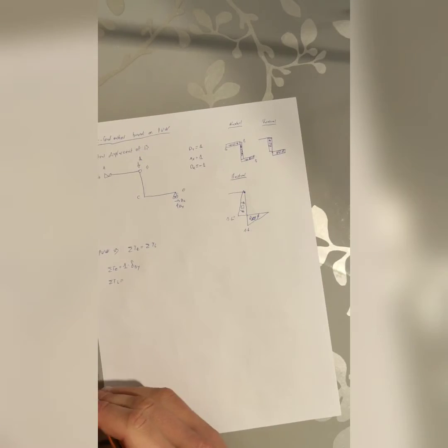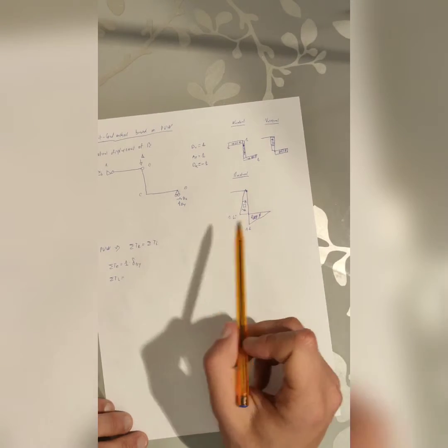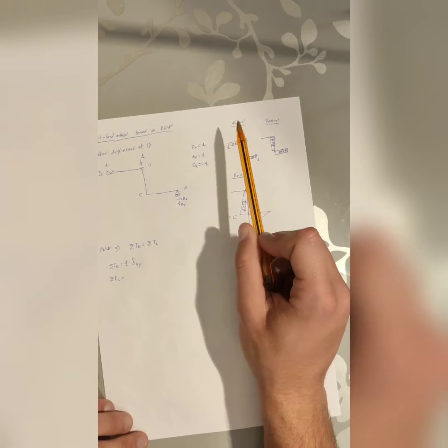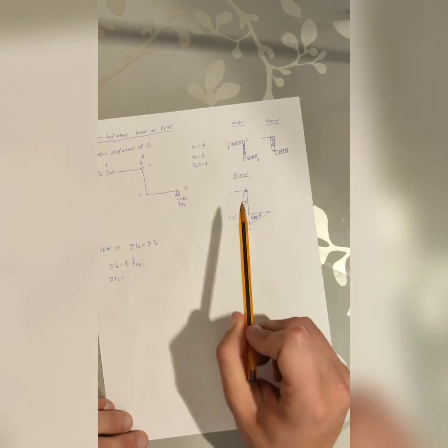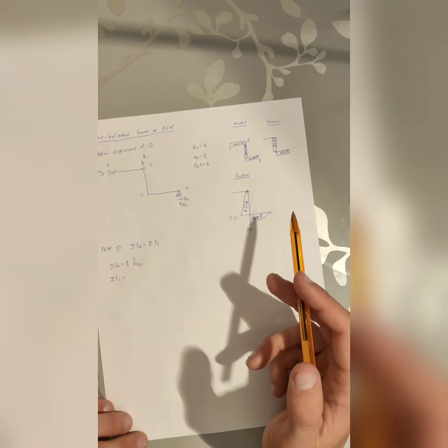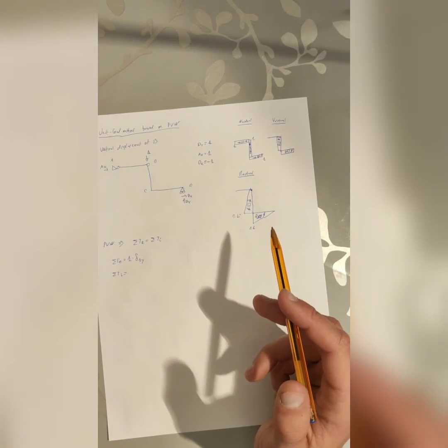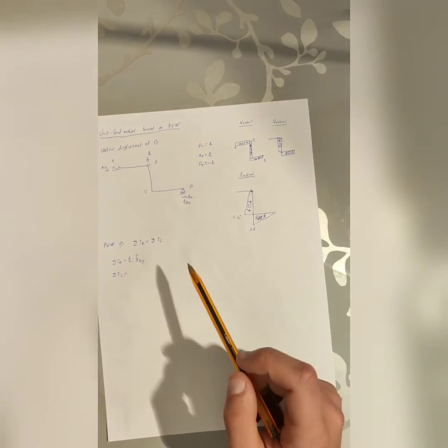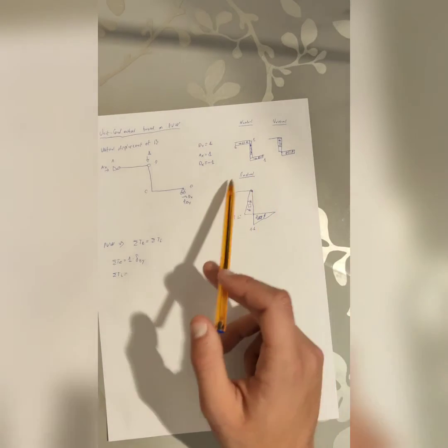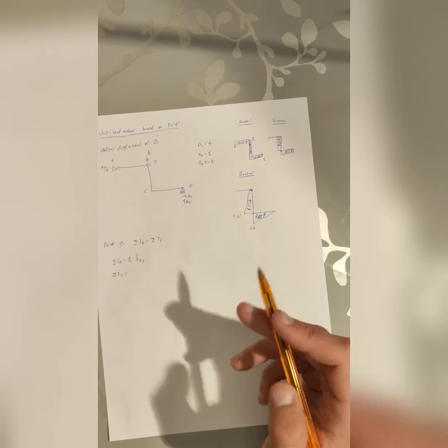And the internal work, as we have said before, takes into account the normal force, the shear force, and the moments. But since we are taking an axial rigidity as infinite, and for shear as well, we only take into account the moments.